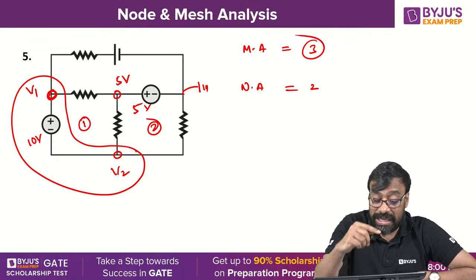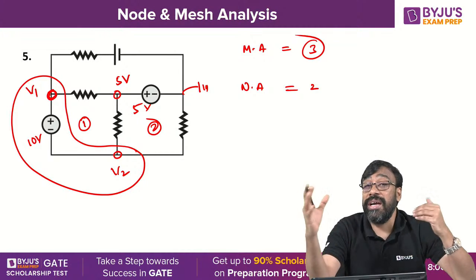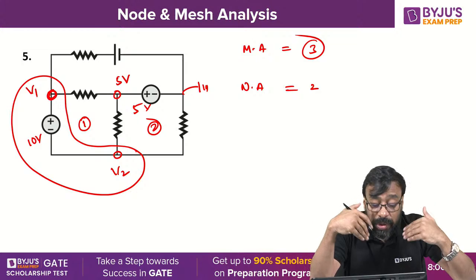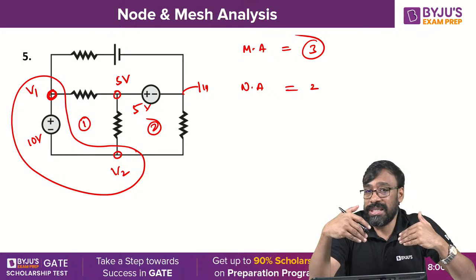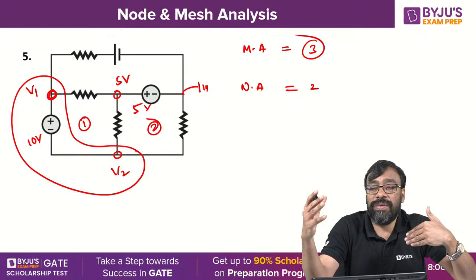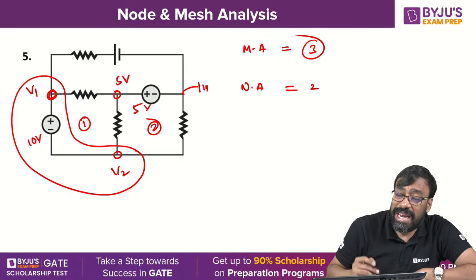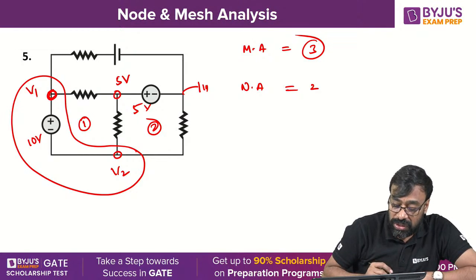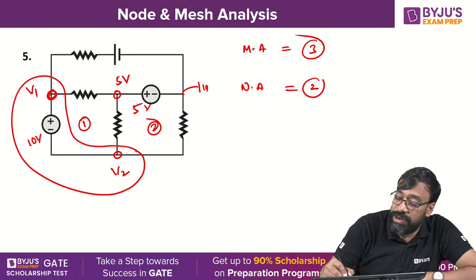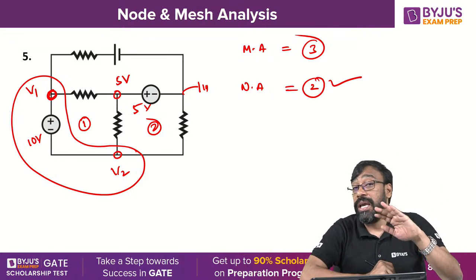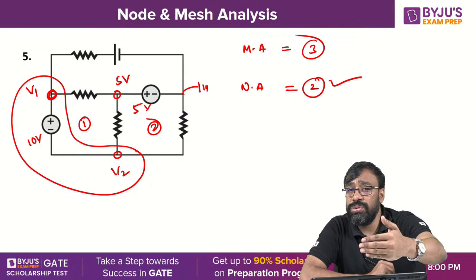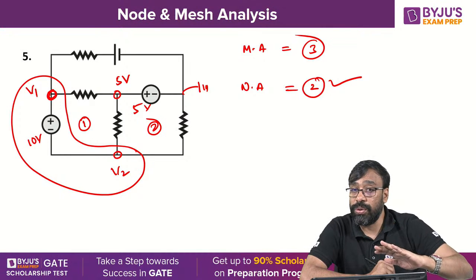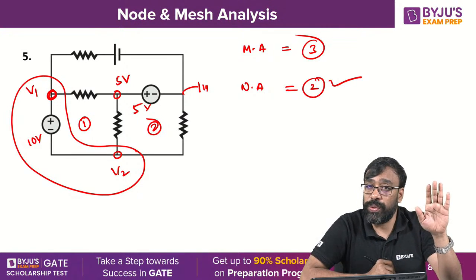You understand, all of you? Because there are 2 ideal voltage sources located at different places, when there is no common node between the 2 voltage sources. Okay, the 2 are differently placed. So at such a time, if you want to escape from the supernode, it cannot be possible. So now here, once again, 2 equations are mandatory. Even though you shift the reference node to some other desired location, still it will form the supernode.